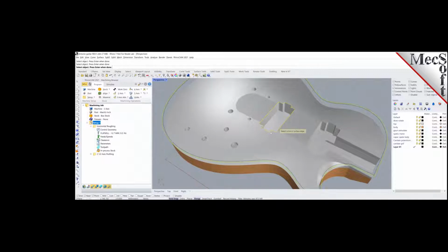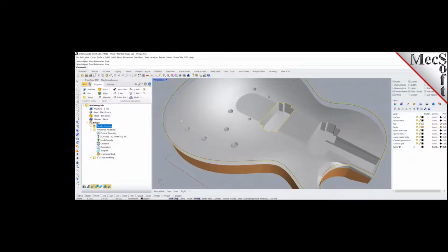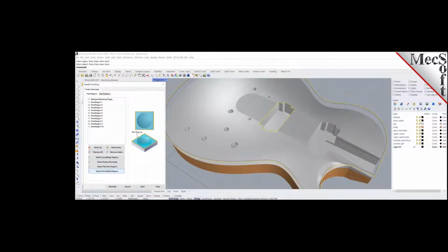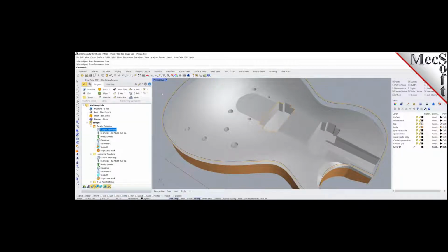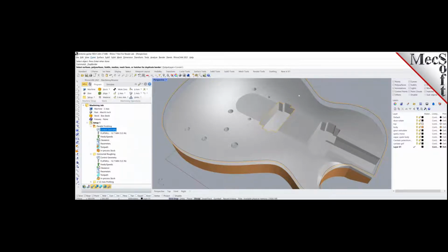Yeah, you can use some of the Rhino commands to create curves. So let me run it. Open loops found. See, this is what I was saying. Okay. Yeah, the curve was not closed, so let me recreate them. Let me take out all of these. Then I just have a closed vector operation. Yeah. So let me use the Rhino tool. That's where the power of Rhino comes in. So you can go to curve from objects. You can extract duplicate border, and you can just select that.